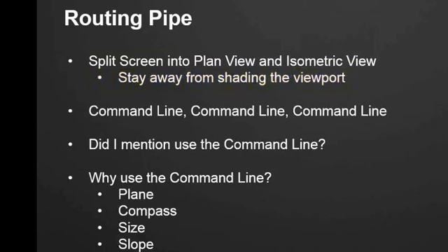The second thing I would say is, always keep an eye on the command line. I say it 3 times there, and then right below it I say, did I mention use the command line? Because I see a lot of people that just click their mouse and start drawing, and they don't really pay attention to what's available on the command line and the options that are there. So we will go over some of those options when we actually get into AutoCAD MEP.